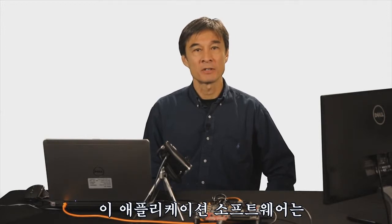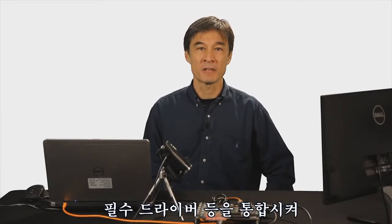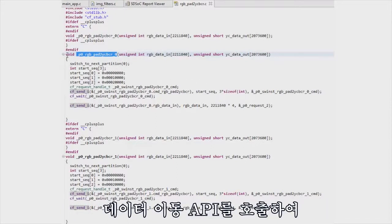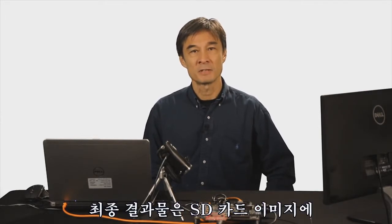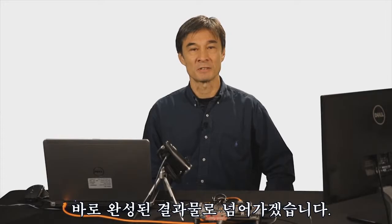Our application software must now control hardware accelerators and implement data transfers to them. SDSoC automates this complex set of steps by integrating the application with any necessary drivers, for example, for DMA. It does this by generating system-specific software code and calls into data transport APIs to implement all data transfers and to control the accelerators. It then compiles and links this generated code with the application. The end result is a complete hardware, firmware, and application executable in an SD card boot image. This entire process takes some time to complete, so we'll jump ahead and look at the finished results.